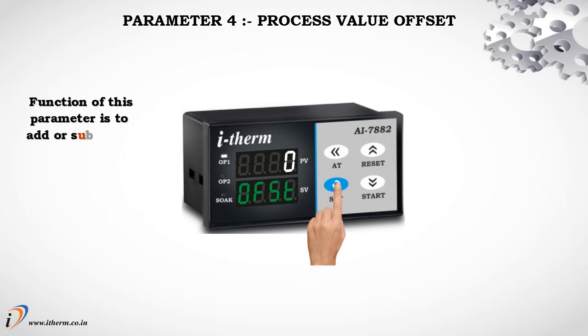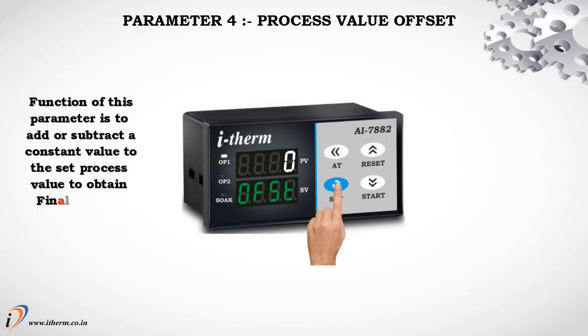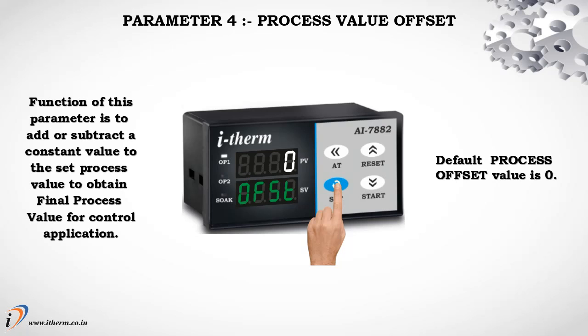Parameter 4, Process value offset. The function of this parameter is to add or subtract a constant value to the set process value to obtain the final process value for control application. The default process offset value is 0.